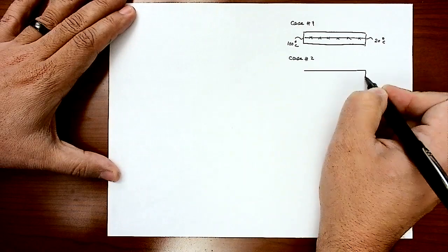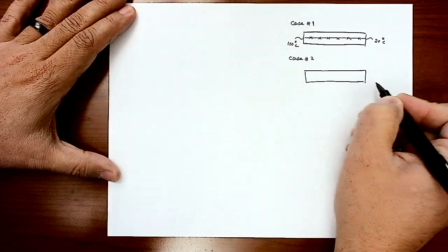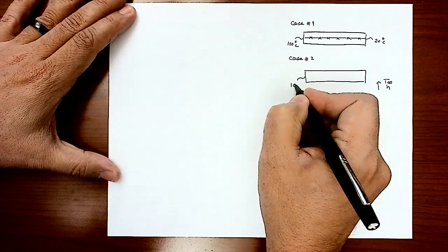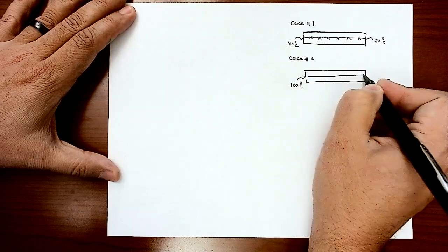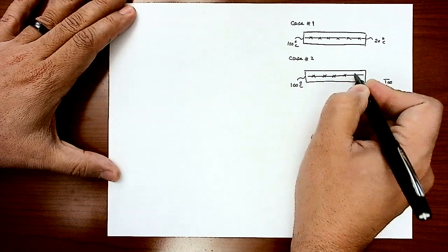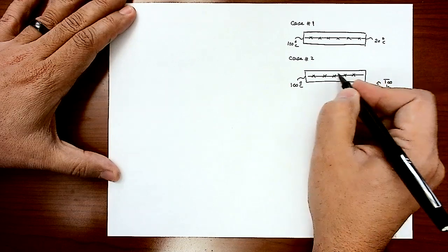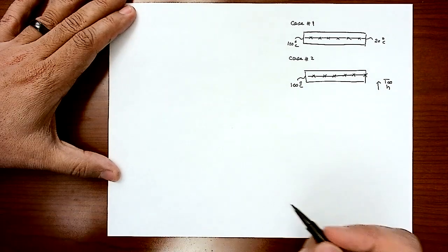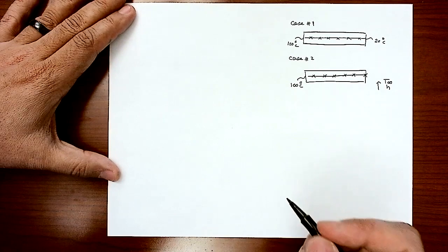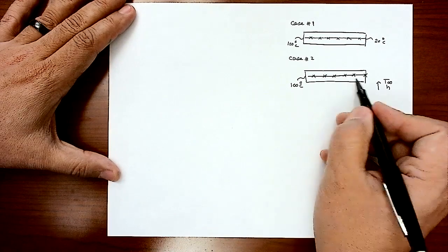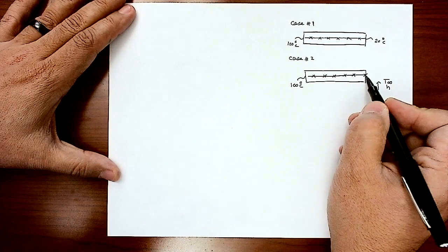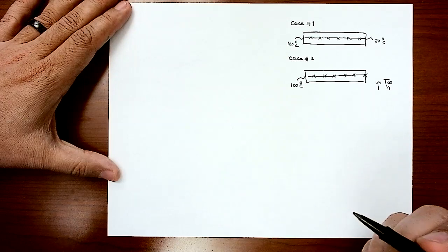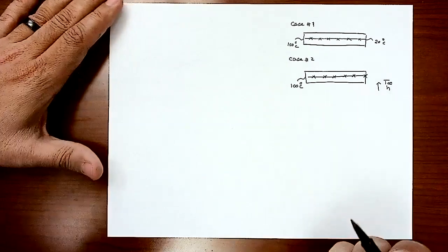In case number two, we did change the boundary condition on the right side to expose the surface to a fluid with T infinity and h, and we kept Dirichlet boundary condition on the left side, also to get the temperature distribution at all nodes. Then we got an extra node on the boundary here. Then we showed that we still can apply the finite difference method for the interior nodes, and when it came to that outside node here, we did apply the energy balance method to be able to get an extra equation for that surface node.